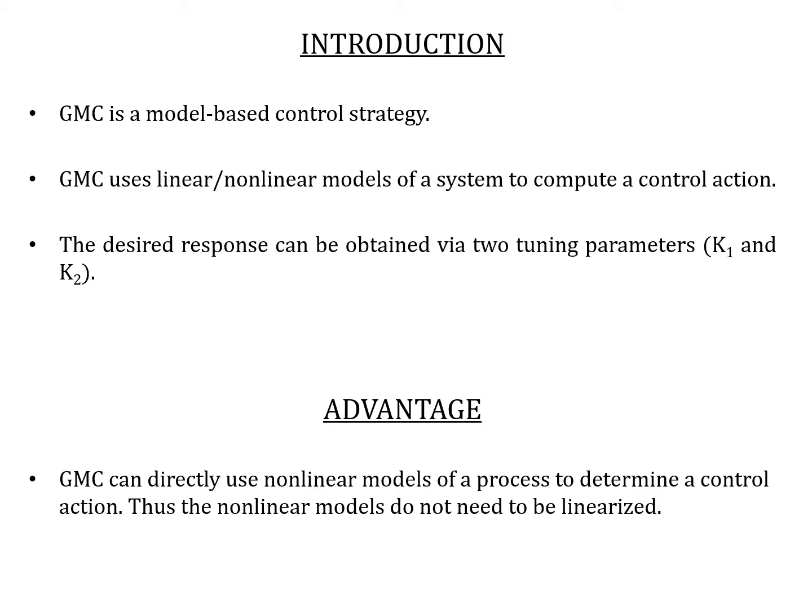As we said before, the accuracy will definitely be lost because a linearized system will work for some region, but for some other system may not be that good and not be generally used. And we may also face stability problems in very non-linear regions and so on. So that's a disadvantage of using the conventional control for non-linear systems.